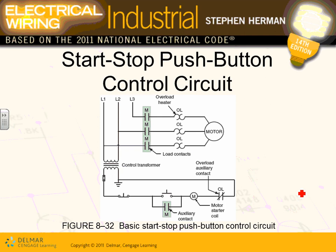Okay, here are my contacts, guys. Start, some push button here. We have an auxiliary holding contact. This is what we call a holding circuit. We talked about this one before, guys. You push the button right here. I want to bring to your attention, guys: can you see the M here and the M here? This coil is driving these contacts.